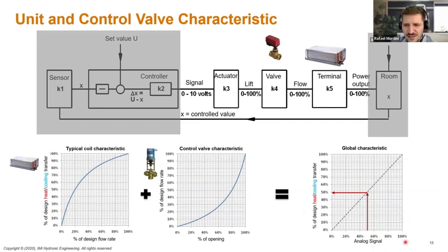In this case here, the slide is showing 50%. We can take a look at our curves here. So we need 50% of cooling or heating power. It means that we just need 20% of the flow rate. So I will develop a control valve that with 20% of flow rate has the valve open at 50%, you know? One compensates the other. In this way, we have this linearity here. That's our goal. But at low load conditions, this here will be deformed, unfortunately.